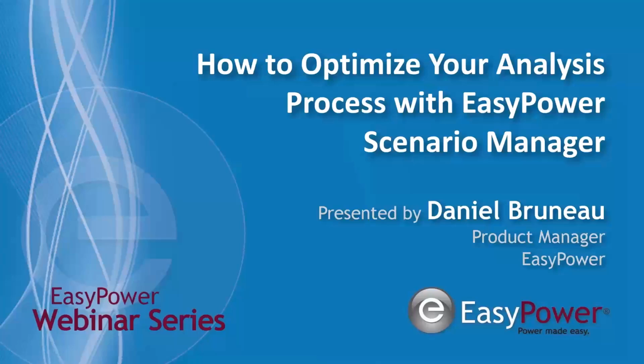Sure. Any changes to the base case? Yes. The easiest way to think about how this works is that your base case is just that, your base case. When you create a scenario, what EasyPower is doing is recording the changes you make in that scenario. Maybe I change the utility contribution, add a piece of equipment, or delete equipment. That's all recorded and then saved. When I open that scenario again, it's effectively just playing those changes back onto the base case, right?